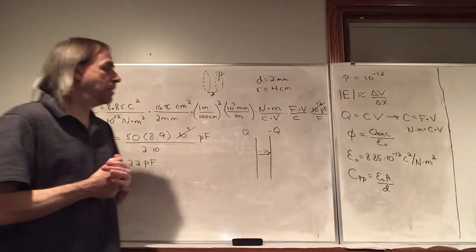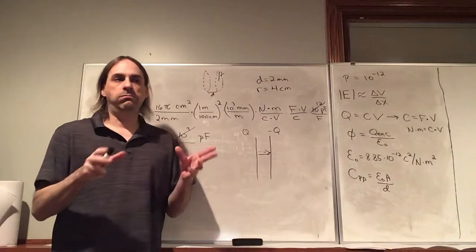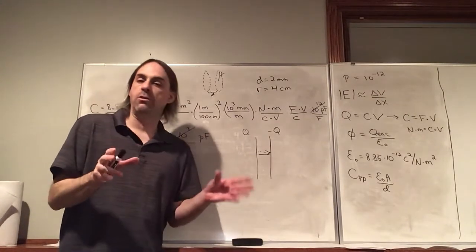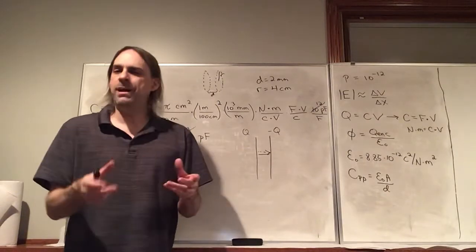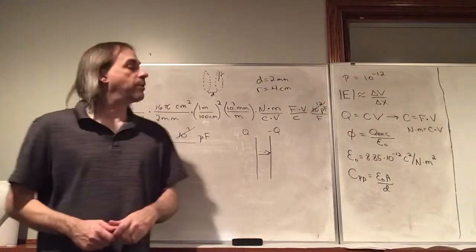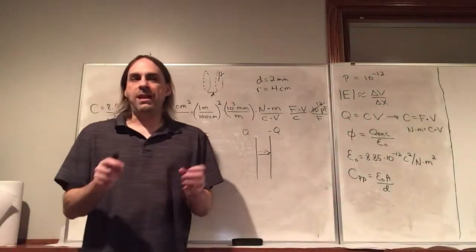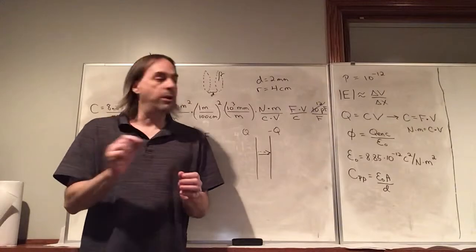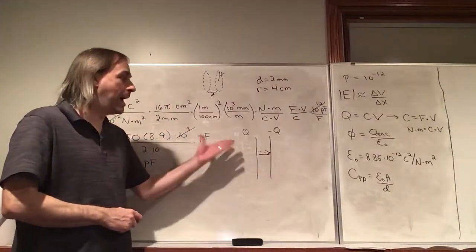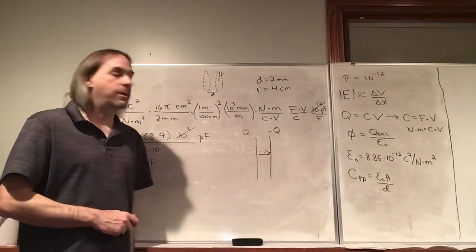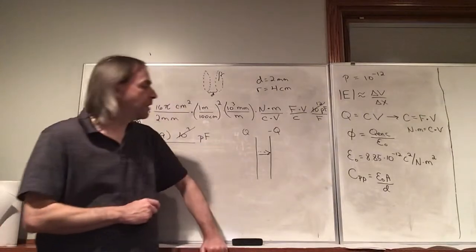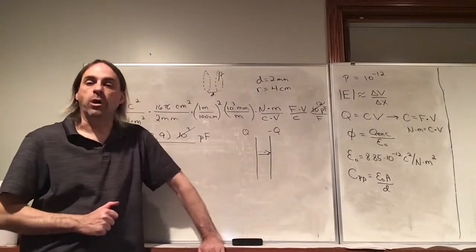And by combining them, one prevents high frequencies from going through, the other prevents low frequencies from going through. And it depends on what the value of your capacitor or the value of your inductor is. But you can set it up so that there's a narrow range of frequencies that can exist in that circuit. Because if they're too high or too low, they're either blocked by the capacitor or the inductor. And this is kind of how a radio works.